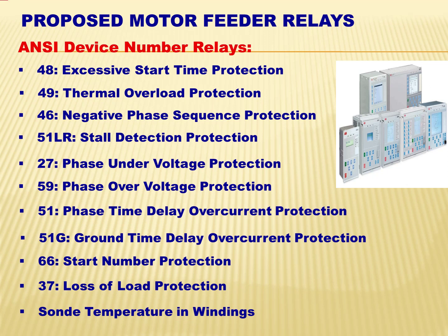A set of 3 is normally used, and a second set of 3 is specified as spare detectors. The active elements are wired to a threshold relay that gives the first threshold as an alarm and the second threshold as tripping when the temperature is exceeded.